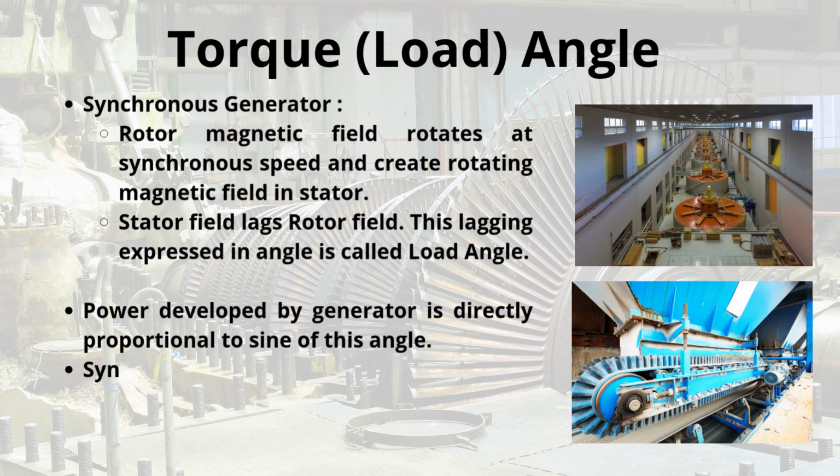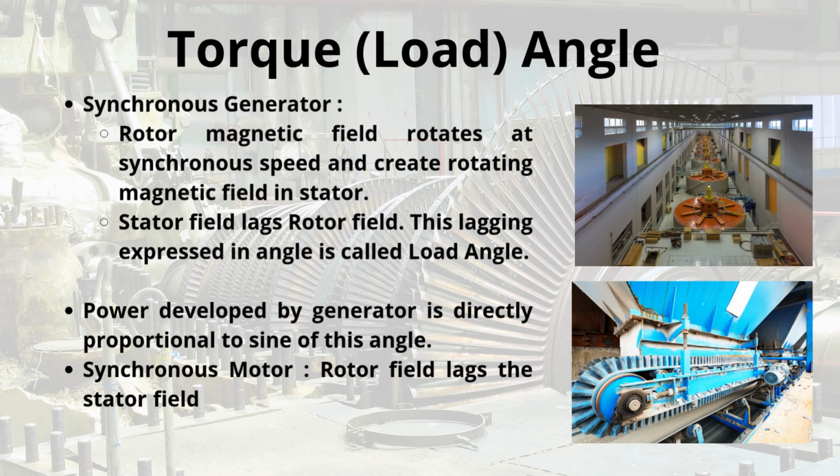And for a synchronous motor, similar idea, but it's called torque angle. Yes, an analogous concept. The stator field rotates, pulling the rotor's field along, making the shaft turn. The rotor field lags behind the stator field. That difference is the torque angle, and the torque the motor develops is proportional to the sine of that angle. So this angle really matters when you're talking about the machines themselves, generators at the utility, big industrial motors. Precisely. It's internal to the machine's operation.